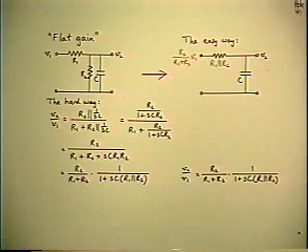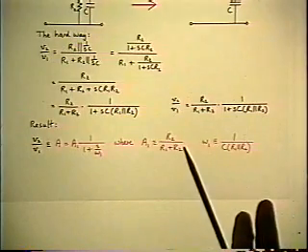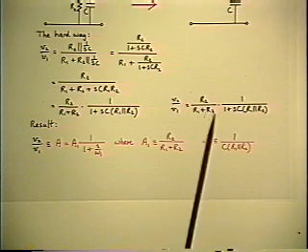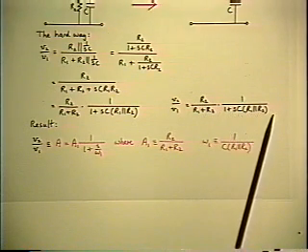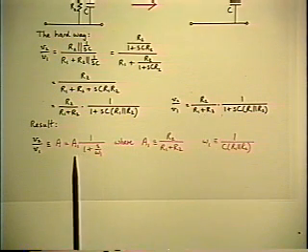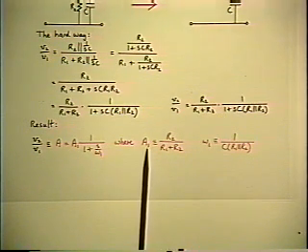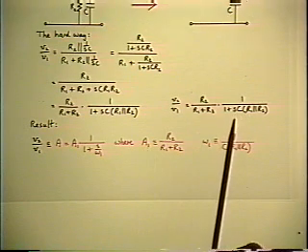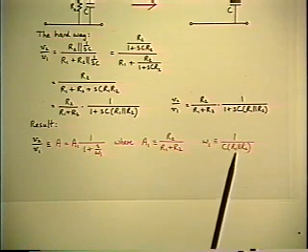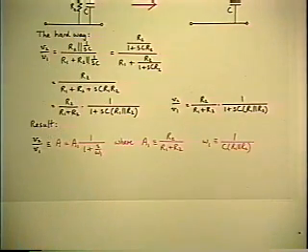Well, whichever way you do it, the next step is to identify the salient features. Salient features means the coefficient in front and the coefficients of the S terms. Because the coefficient in front has the interpretation of a gain, in this case a loss, but it's a gain factor. So call it some symbol like A1. The coefficient of S has the dimensions of reciprocal frequency, so you define it as the corner frequency. In this case, the capacitor together with the 2 resistors in parallel.